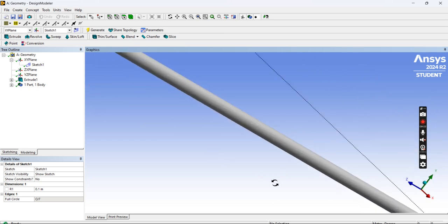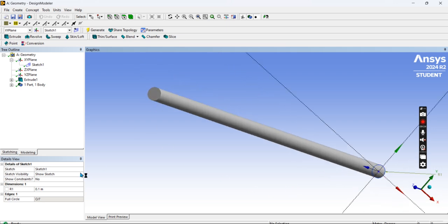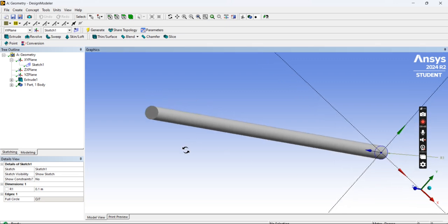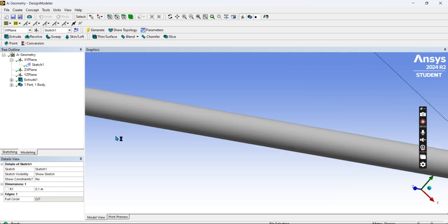So first let us name these selections here. Now remember an important thing. You can see four types of selection icons: point, edge, surface, and body. Here you can see the point icon. If this section is selected, you can only select points on your geometry. This part here is only used for selecting edges.